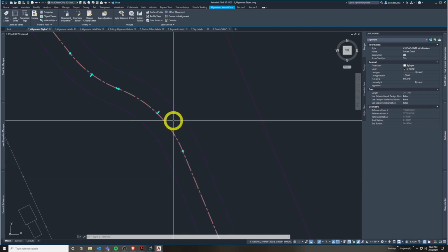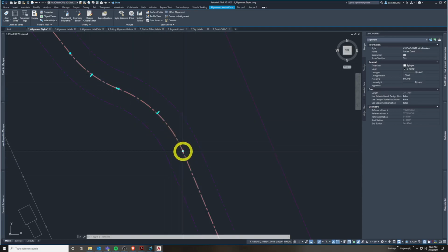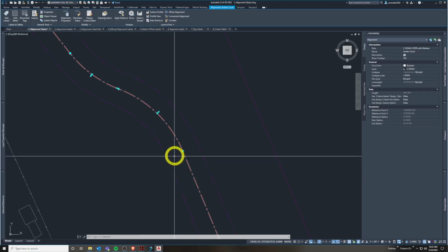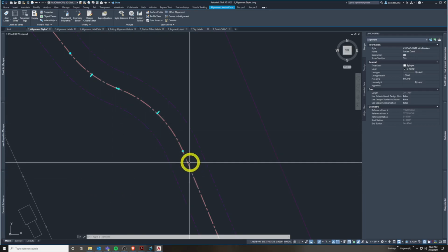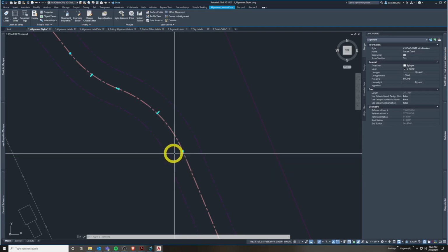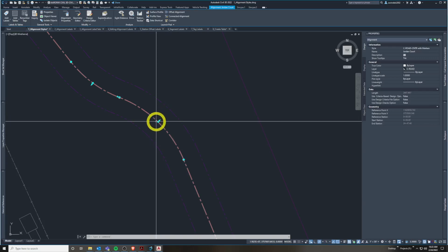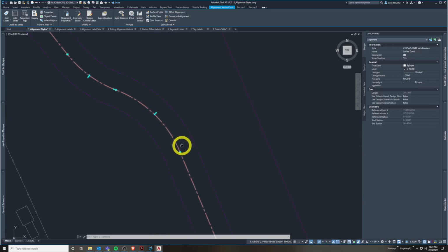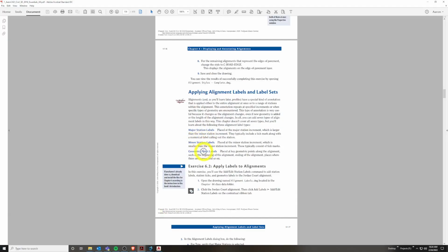They're very common geometries, but the biggest thing is in almost any land surveying and civil engineering application, we try to keep things tangent as much as possible so they can be easily reproduced and staked and constructed in the field. So that means a 90-degree angle from here to its radius to the center of this curve. When it hits this tangency, it's 90 degrees. So it's tangent to the line. The curve and the line are tangent to each other. So that's very common, but we're going to have horizontal geometry labels for those.